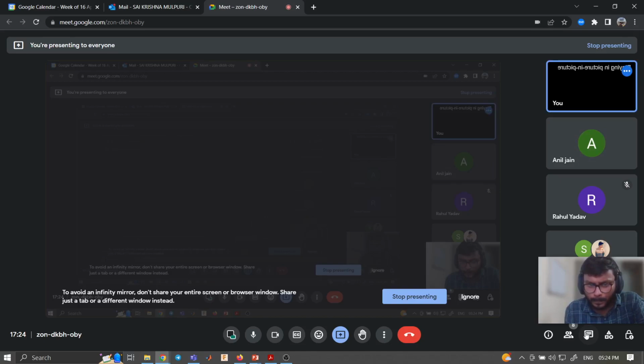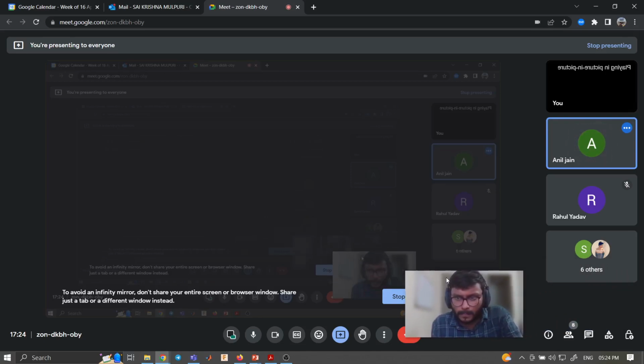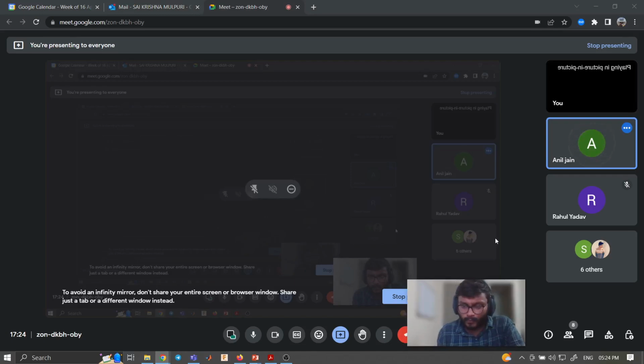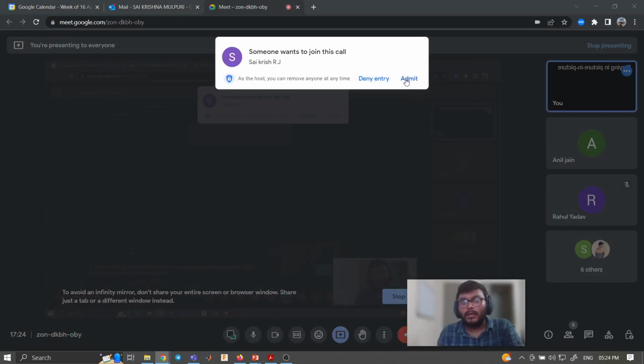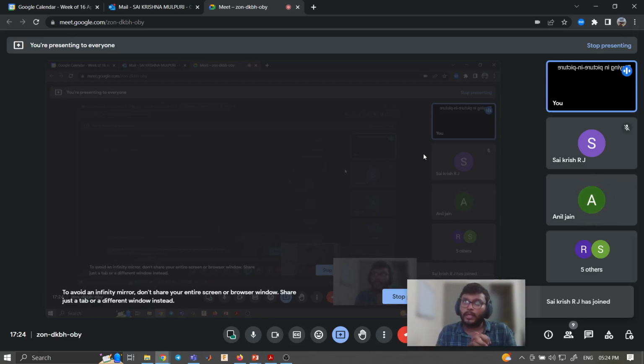Can we not use a synchronous generator for improving power factor in place of a synchronous motor? Okay, you are saying that in place of the synchronous motor, you want to use a synchronous generator. You can use that, but the problem with the synchronous generator is it has to supply back to the load. For a generator, you have to give a prime mover input. You have to rotate it, and that is another mechanical energy you have to give.